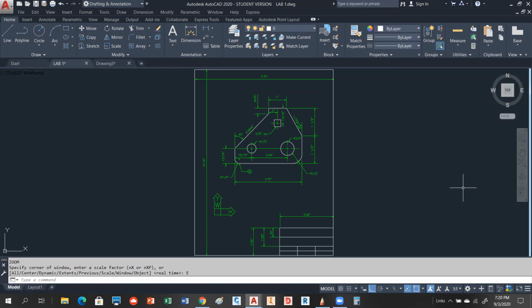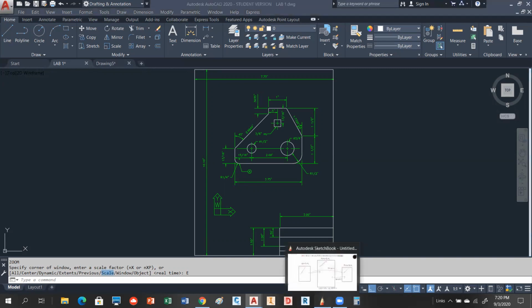Yep. The other thing that a zoom extents very often will do, or the zoom all, sometimes they force a regen also, whether you like it or not. So you may get a regeneration happening if you do that, okay? So that's a possibility. All right, so we're gonna look at scale next. So there's several sub options for scale. Let me kind of explain that here.